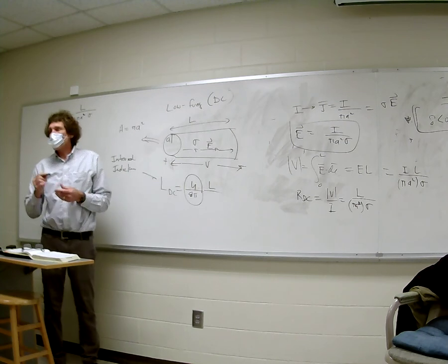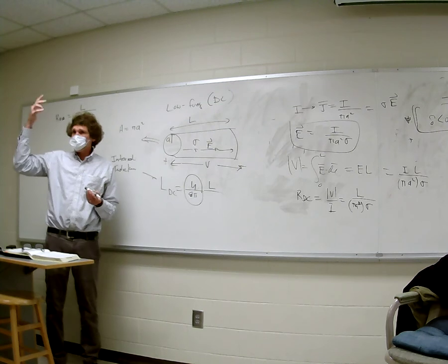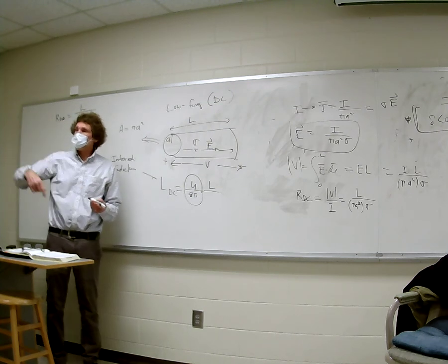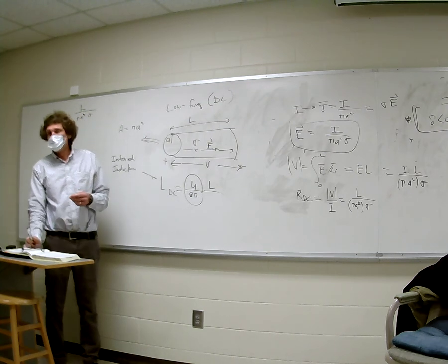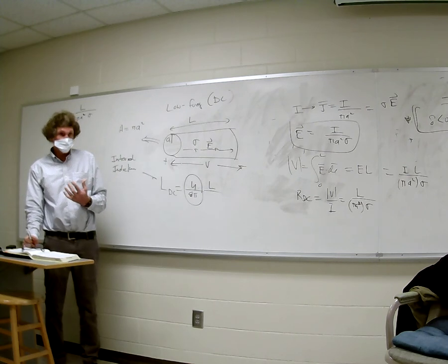But we know when you have a wire, most of the energy, just think of the field lines, is that we have H fields all over the place, right? H fields cause an energy density of 1/2 mu H squared, magnitude. Energy density integrated over the region where the H field exists would give you the total energy, which is many orders of magnitude at times greater than that.